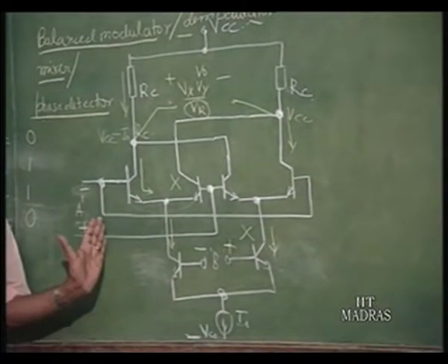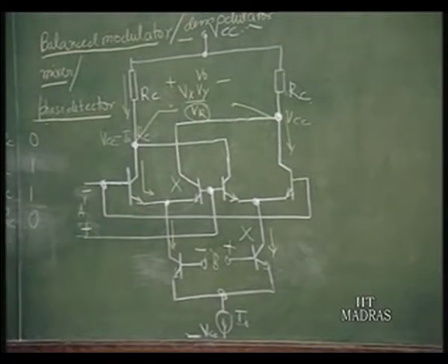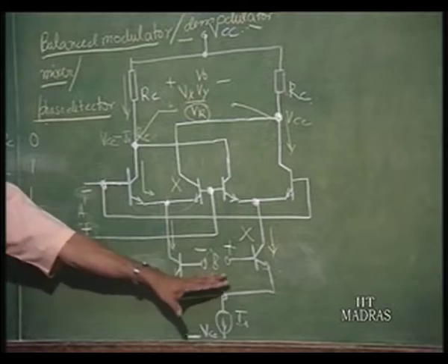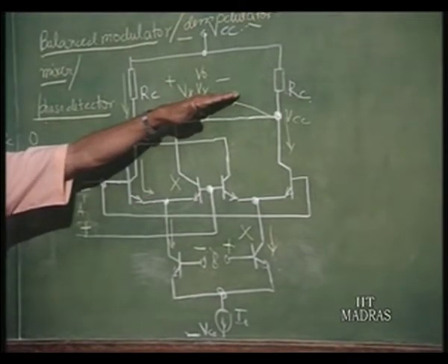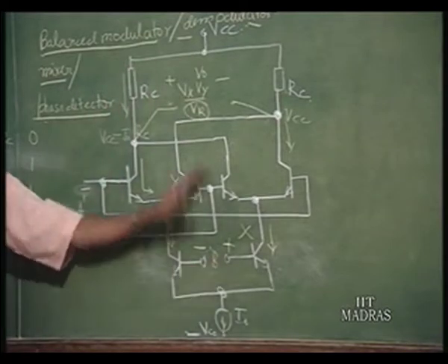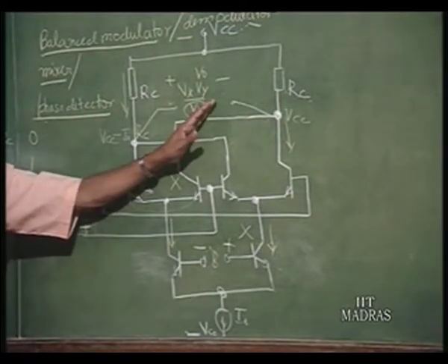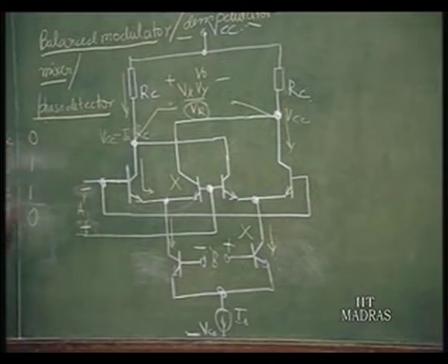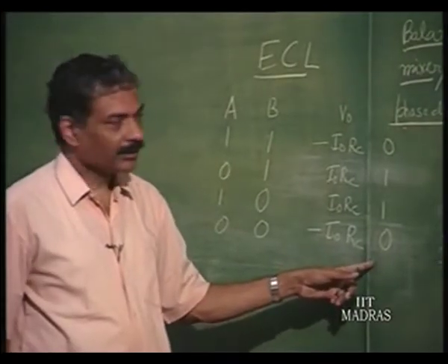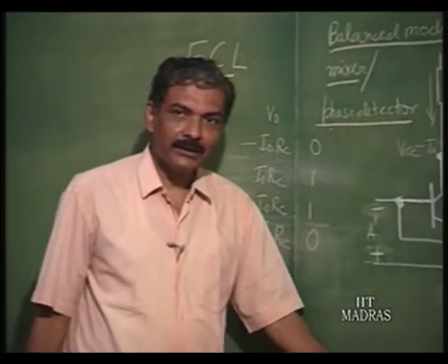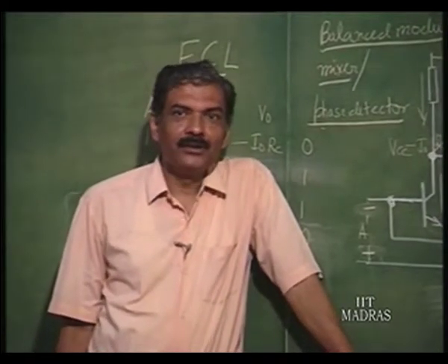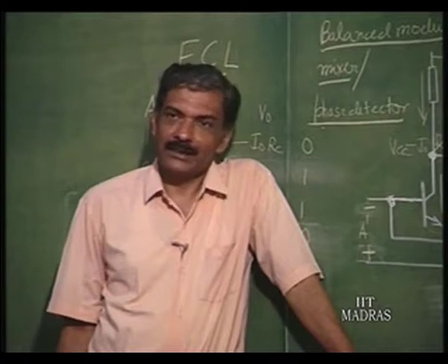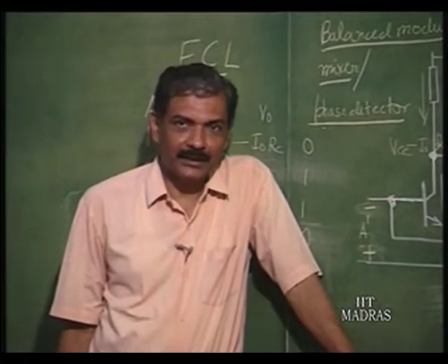and then you can treat this as a logic circuit and assume that this is a square wave, this is a square wave, and output is a square wave of, let us say, if these two are of the same frequency, this will be of double the frequency here, because of the number of times it changes here, and therefore, this is going to be an XOR gate, which is also going to be useful for phase detector application, linear phase detector.